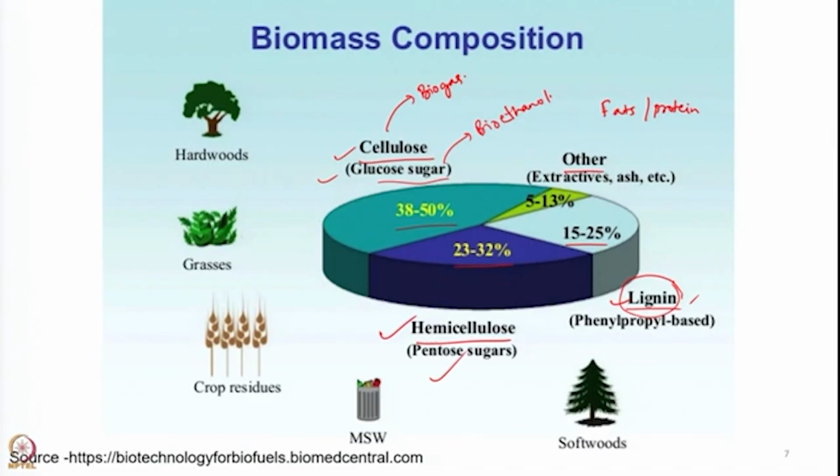It is important to understand that gasification and pyrolysis are independent of composition, but they have a limitation on moisture level. The moisture level should be low and the feed reasonably dry, so that it can be used effectively and efficiently. With this I conclude the first module, and we will continue with the next module in understanding the thermochemical conversion processes, gasification and pyrolysis.